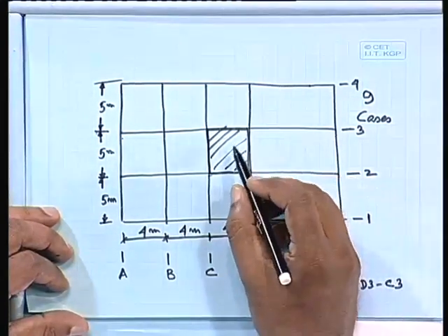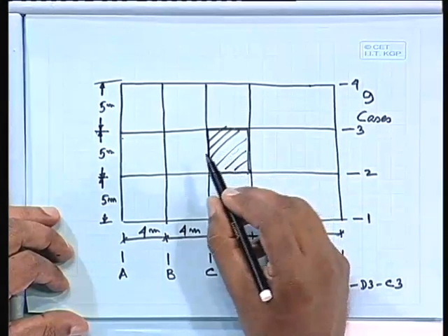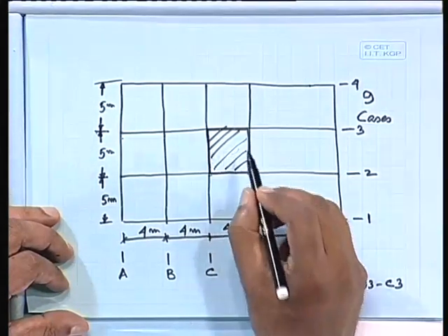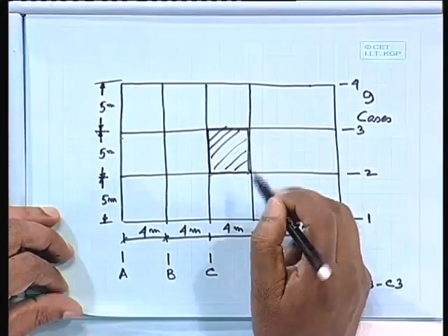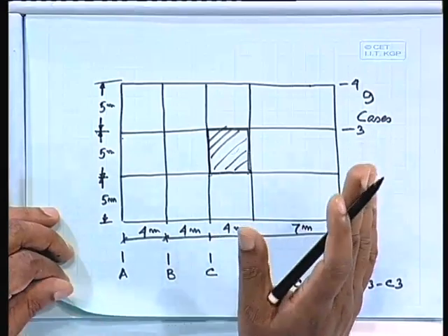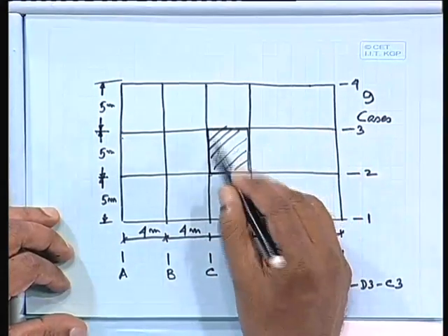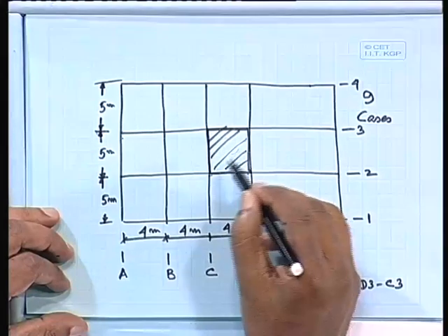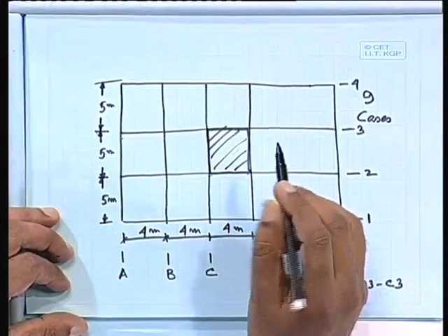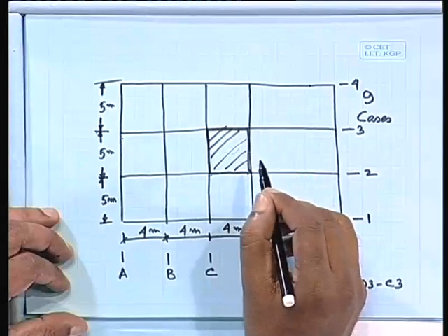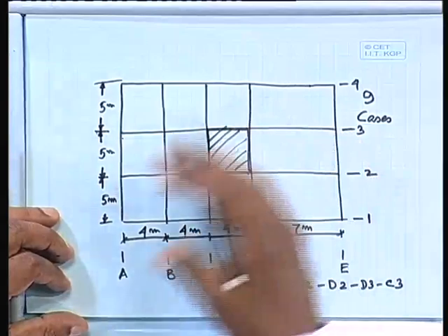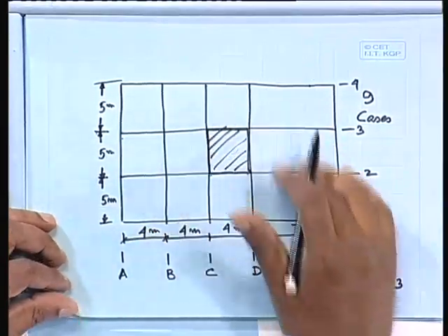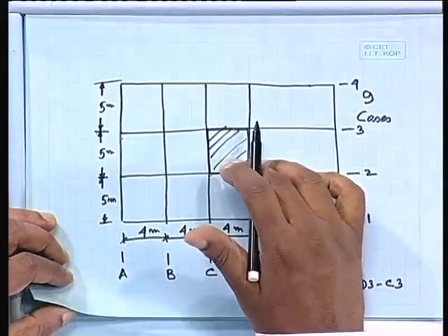So bending moment at span and at support in the shorter direction, bending moment at span and support in the longer direction. We have to check our design on the basis of that. That means we shall get different values of moment. So we shall take the maximum moment out of the 4, then we shall get the depth, and then we provide the reinforcement for the other values. So this is the general procedure to provide the reinforcement.